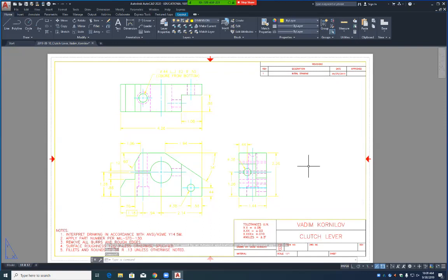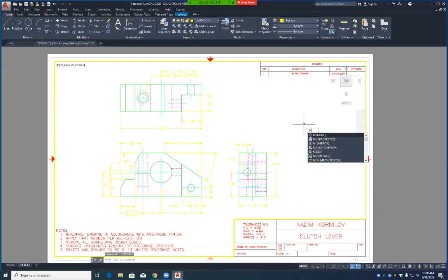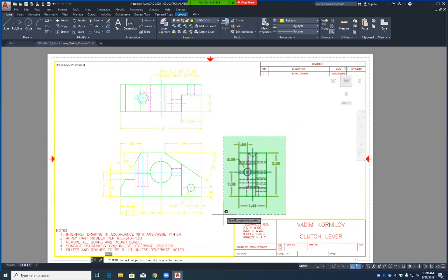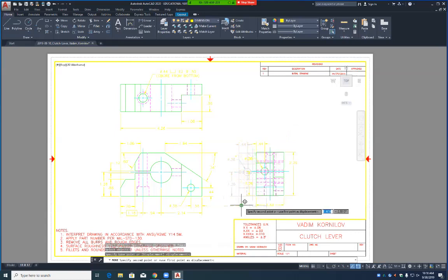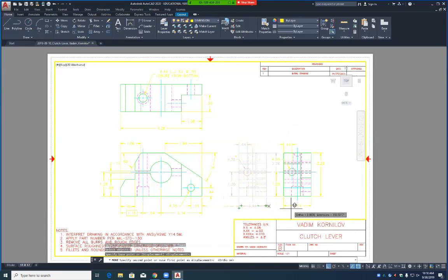Keyways are usually square, and so this is how a keyway is dimensioned, usually 0.4 by 0.2 keyway. That means that 0.4 is the overall width, 0.2 is half of it. So 0.2 is what at 0.4? Half of it. So that means that from here to here is 0.2, from here to here is 0.4. That's all it's signifying. That is it.